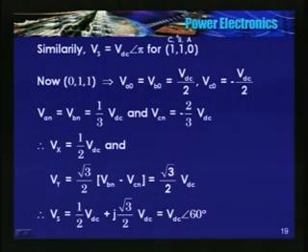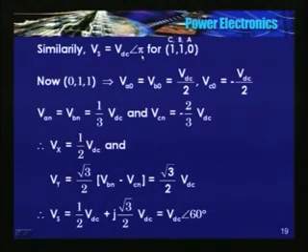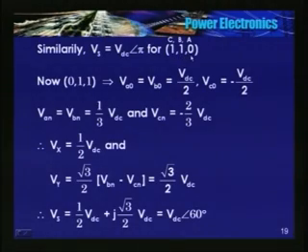So for 0, 0, 1, it is Vdc at angle 0. Therefore for 1, 1, 0, which is the complement of this, my vector is at 180 degrees to the previous position, so Vdc at an angle pi. If you are not convinced, just work it out, you will get this answer. More about the space vector PWM technique I will cover in the next class. Thank you.